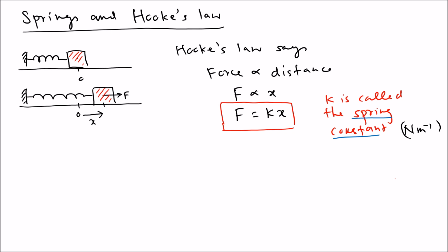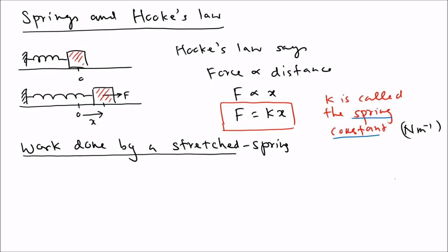Good. Now let's go to the next part. Let's try to find the work done by a stretched spring. You can stretch a spring, and how much work does it need? The same situation that we have above: you have a natural position, and you're going to pull x distance from it. We know that the force is given by kx. So we consider this as a varying force and integrate using the formula that we used before.